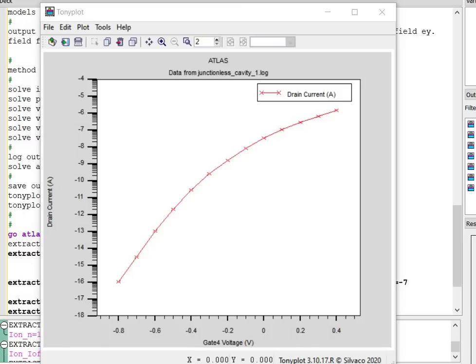In case of charge plasma TFET, the variation is in the on current, but in the junction-less TFET, the variation is in the off current. The sensitivity criteria in case of charge plasma TFET is applied at the on current, and in the case of junction-less TFET, the sensitivity criteria is applied at the off current. I will explain in detail in the next figure.